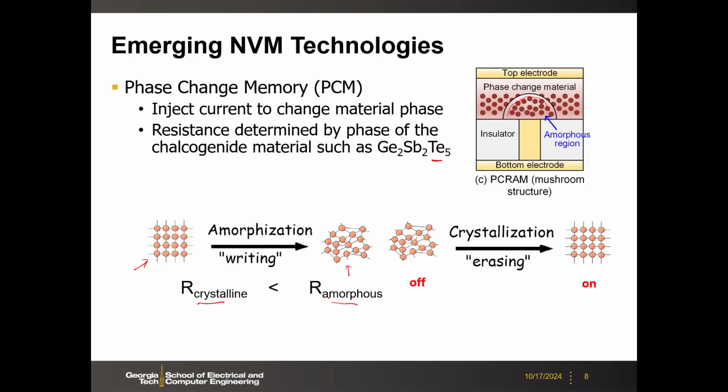And then how do you get this local heat to the system? Then you need this kind of structure, let's say passing the large current based on the Joule heating, right? You pass current, then you heat up. Then by controlling the current flowing through that device structure, you can determine the crystalline and the amorphous states. So this is a phase change memory.